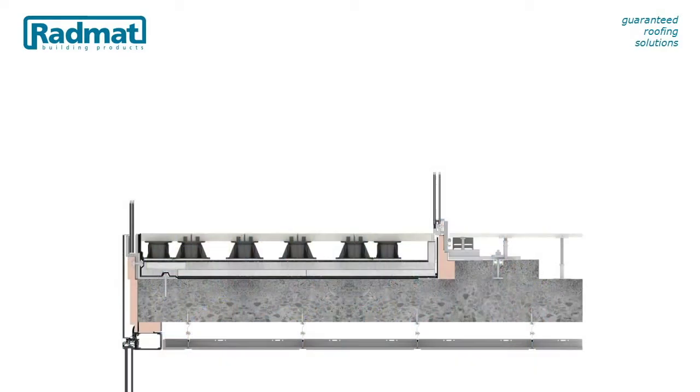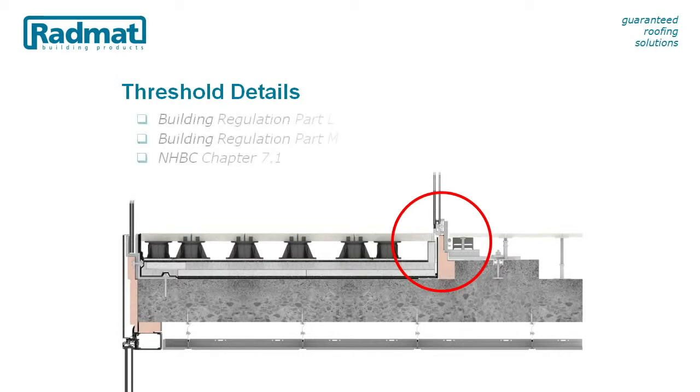We will now move on to looking at some common detailing, starting with threshold details. Here, the requirements to comply with Building Regulations Part L, Building Regulations Part M and NHBC Chapter 7.1 can cause design and construction issues when putting balconies over heated space. Typically, the key conflict is the thickness of EPS or XPS insulation required to meet Part L, impacting on the level threshold required by Part M and/or the drainage zone required by Chapter 7.1.